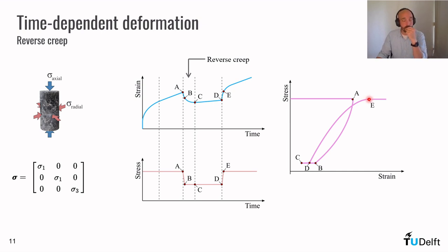So this is very characteristic of reverse creep. When we have an unloading and reloading path on your experiment, and you look at the stress strain curve, if you see something like this, it is a signature of reverse creep. It presents all those features here.